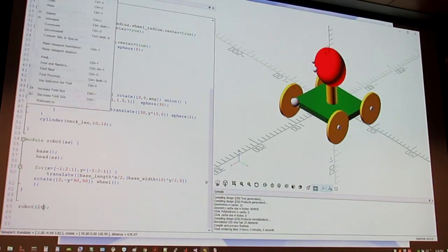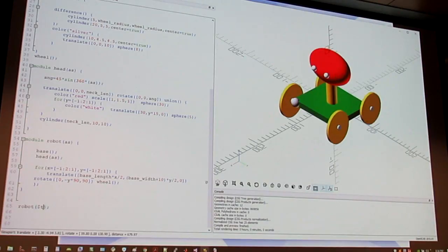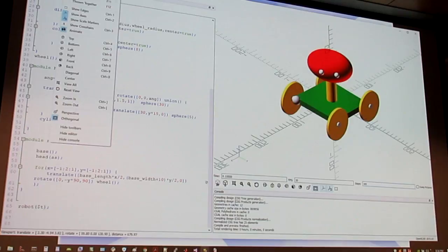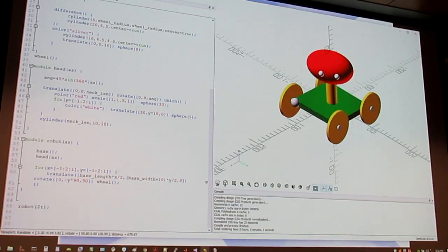If I add that, and I turn on animate mode, I can now specify, let's say I want 30 frames a second, and I want 100 frames. It now animates my model. Nice, so we can check motion. You can actually save these videos out and create a video from the frames. So if you've got motion and moving parts, you can simulate and animate that to see what's going on. So that's the most basic steps of what you might want to do.